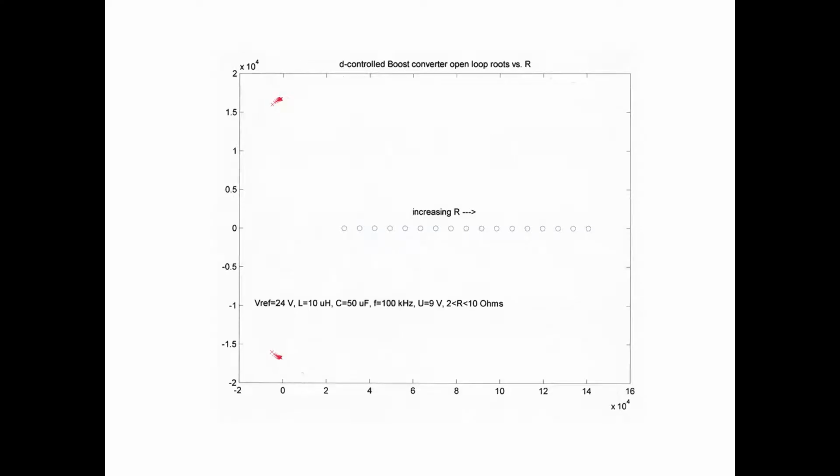The poles, and in the right half plane, these are the zeros in the right half plane. The location of the 0 moves with different values of the load resistance. If I look at the locations of the poles, they move with the load resistance. And what will happen is as R gets bigger, this thing gets less and less damped. The open loop poles are moving towards the j omega axis, which is right here. Okay? Why does it do that?